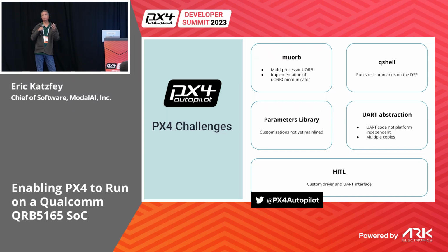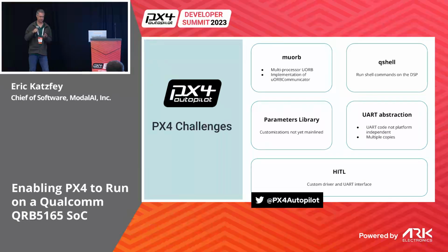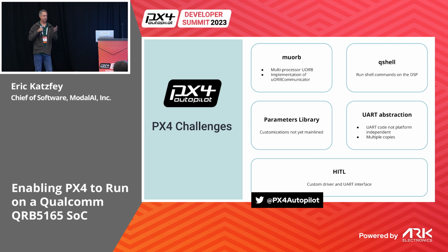This is more of a difference of the OS. If you look at the QuRT operating system running on the DSP, it doesn't have all those POSIX UART commands, like how to set the baud rate and all that. That stuff is copied all over PX4. We have to abstract that out into a PX4 abstraction of UARTs, and then that will allow us to tie directly into what the QuRT OS supports.